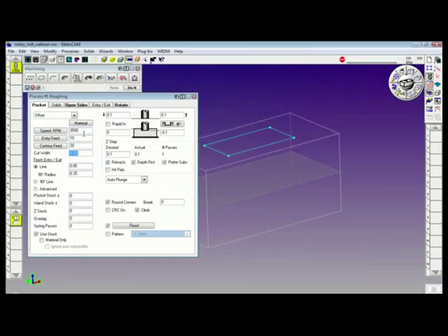My cut width is defaulted to 0.22. 0.22 is the length of the flat at the bottom of the end mill. Remember, we defined it with a 30 thousandths radius, so half the end mill is 250 minus the 30 thousandths radius. The cut width equals 220 thousandths. I prefer to use cutter radius compensation, so I introduce cutter comp with an entry line and an entry radius.